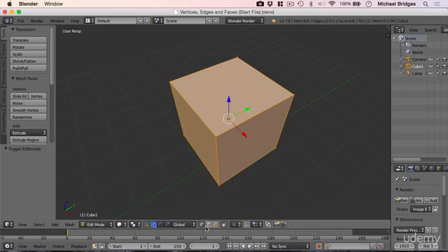On the 3D header bar, you have 3 buttons next to one another: vertex select, edge select, and face select. When vertex select is selected, we're able to select each one of these vertices individually. The same is true when edge select is. We can select all the edges, and finally faces, you've guessed it, you can select faces.